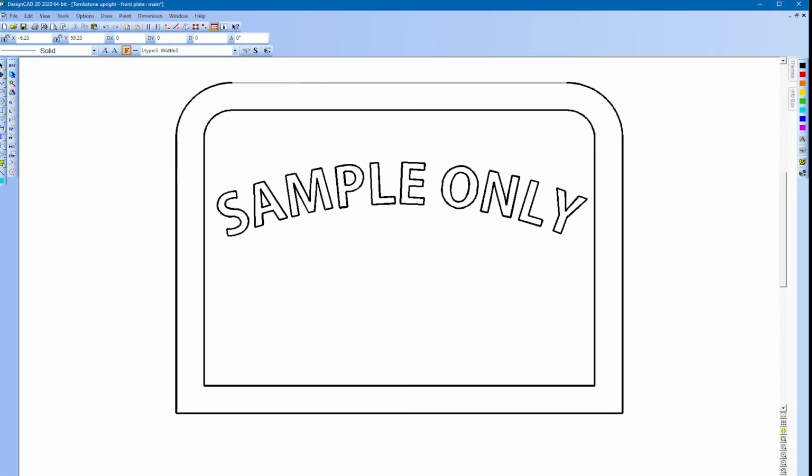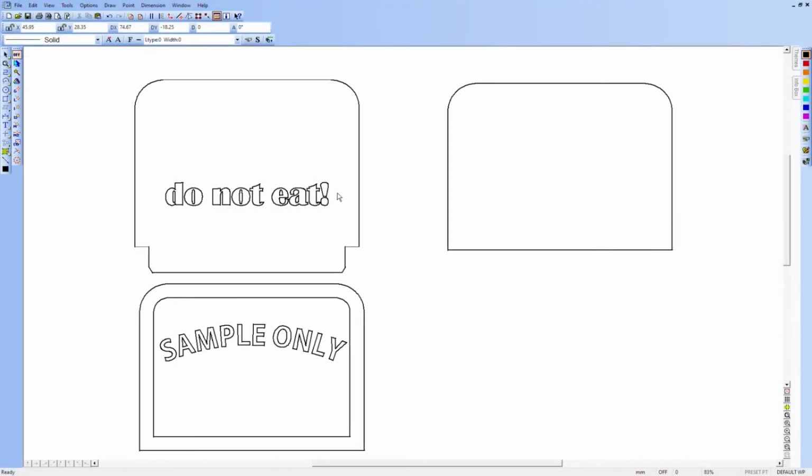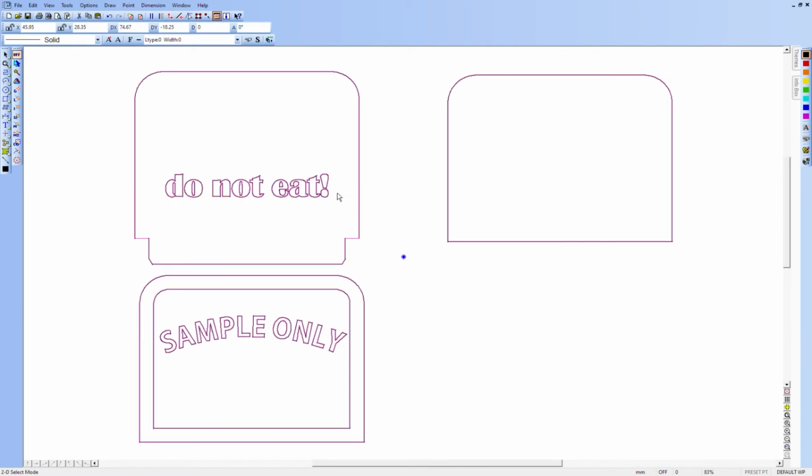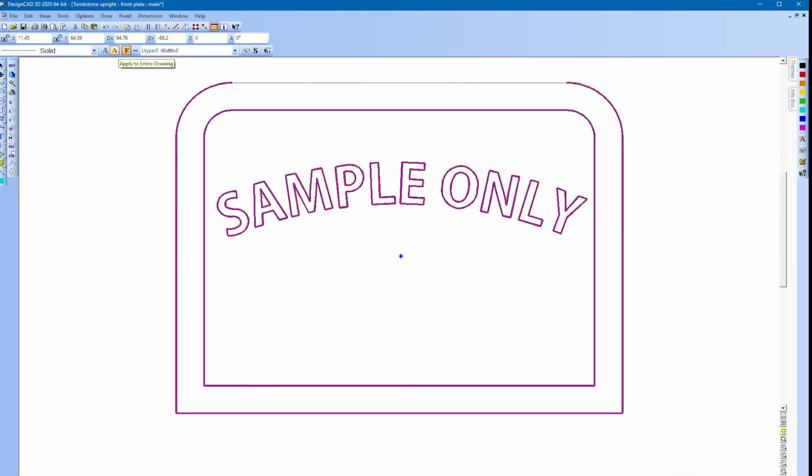When we look where the lines meet, we can see something's going on with the lines. Let's clean them up a bit before we proceed. We select all and then click on black in our color menu at the upper right. We'll then click on the A towards the bottom of that menu to apply the selected color to all of the selected entities. We'll reselect all and then go up to our line style toolbox in the upper left of our screen. It's set to line type equals solid and width equals 0.